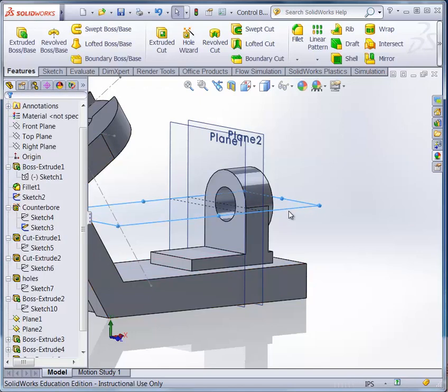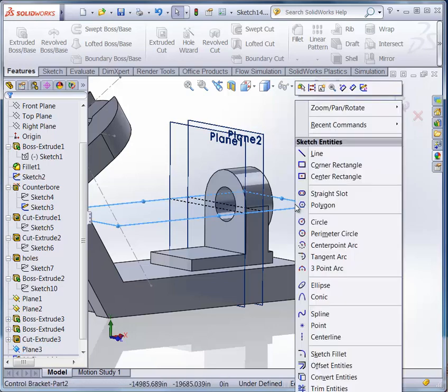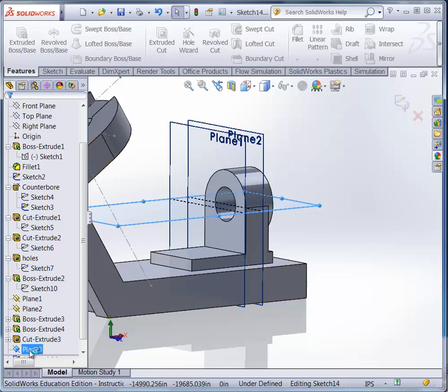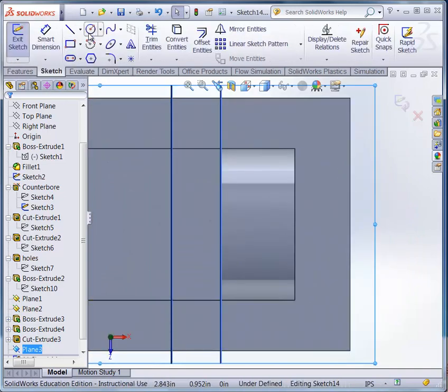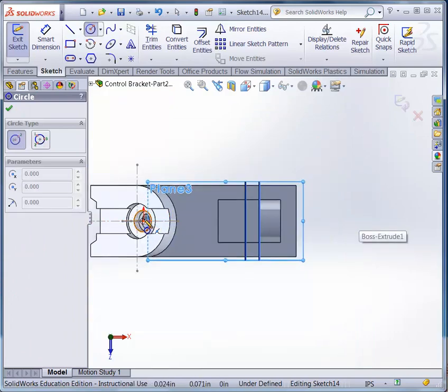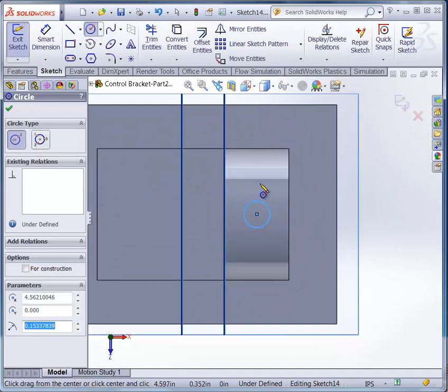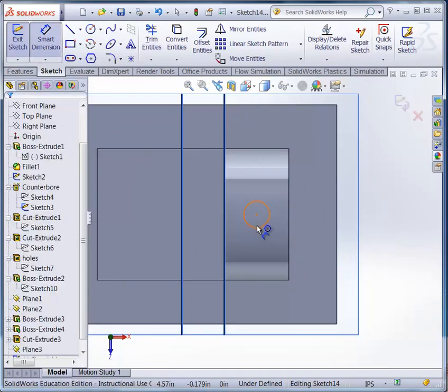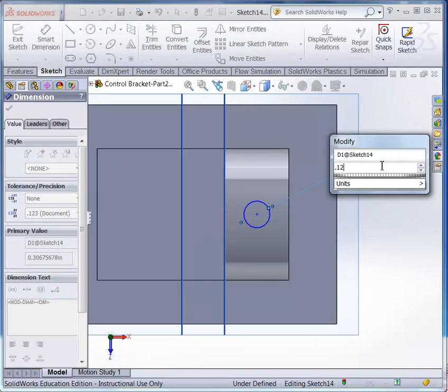And now that I have that plane, I'll create a sketch and get normal to that sketch. Let's do this. Okay. And then over here, we'll create a circular sketch. Again, we want it to be centered with the rest of the part here using the origin. So I'm just going to project right now. I'm not going to worry about trying to create a center line there right now. So that's centered, and then what we'll do is use a smart dimension. Okay, we'll make that diameter 0.125.